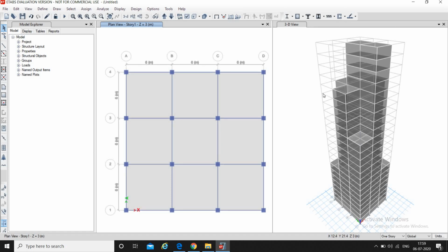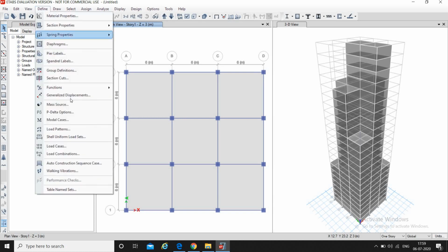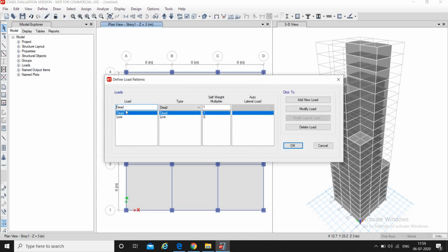If we consider that the wind is blowing from the left side, then it will directly hit some claddings of section A and some claddings of section B, depending on the story. So you have to carefully select the claddings section-wise with respect to each side of the building. You will understand more clearly as we proceed with the steps.